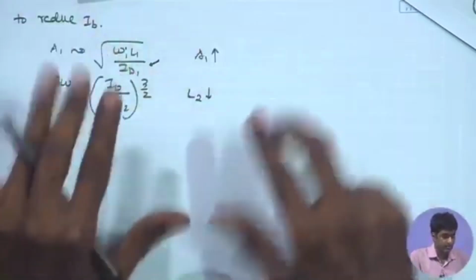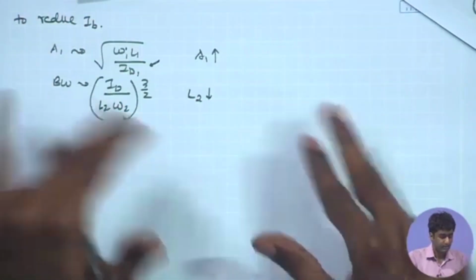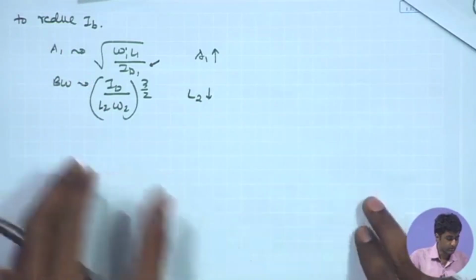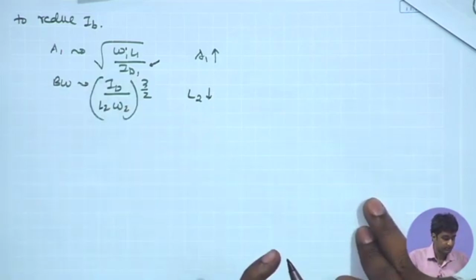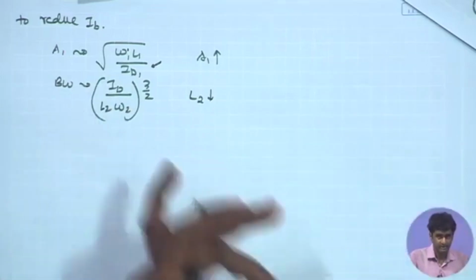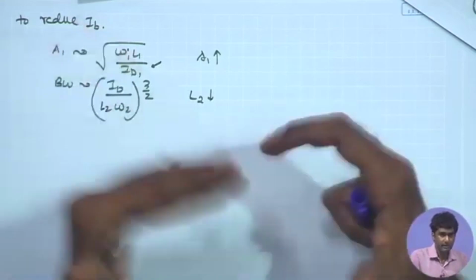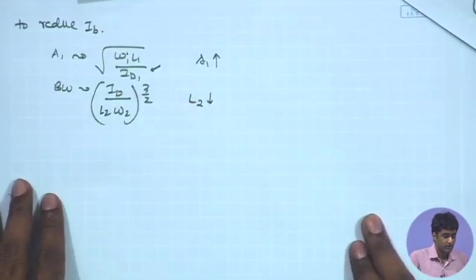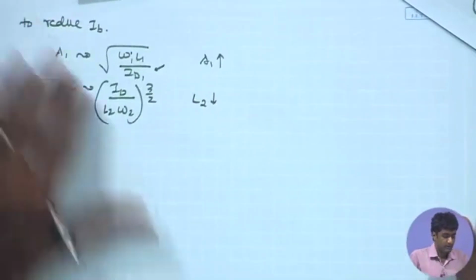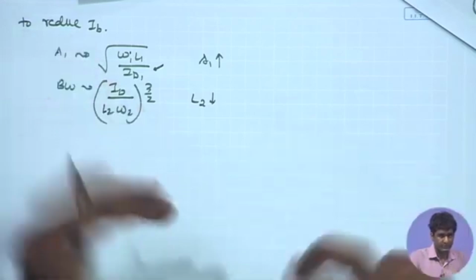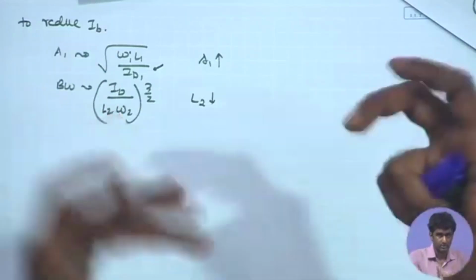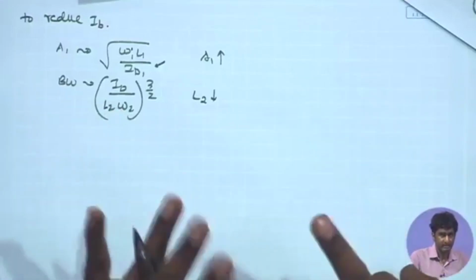So, these are the directions we can take up step by step, and if you are aware of the dependencies, that is, from where the dominant capacitance is coming, from where the significant RO part is coming, which device dimension affects the parasitics in what manner, then we have the right directions we can tweak, and we can make an informed decision about the sizing. Of course, in the simulations, whenever we tweak the device dimensions, we can get the appropriate path based on the intuition, based on the information about the dependencies that we have.